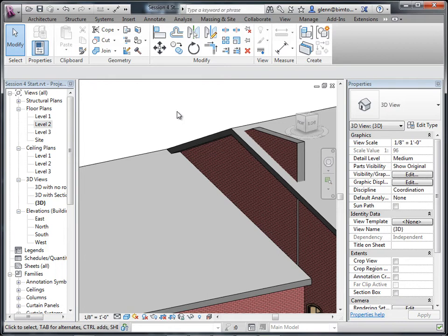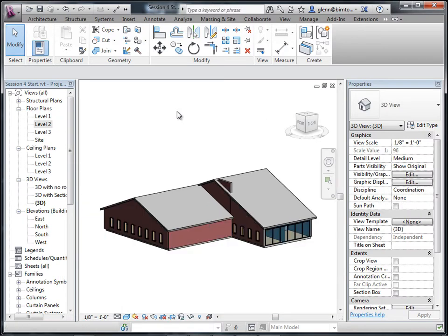What's going on? Because attaching is really a good thing, but attaching is really just automating a process that you could do manually. Kind of like in the same way arraying is just automating the process of copying and putting constraints. That's cool. Okay. Attaching really is just saying, take that wall and let's figure out where the boundaries are that it should come to and just clip off the edges. Okay. So how you can do that when it's not quite right is as follows. Okay, I just need basically a good view that's going to show me that wall. Okay, so I can look at it this way in elevation. I can look at it a number of different ways. Actually, let me even show it to you from the inside.